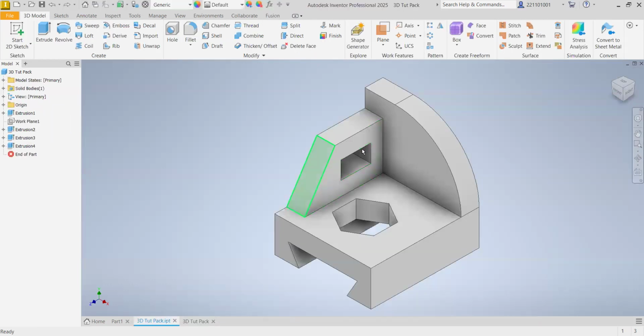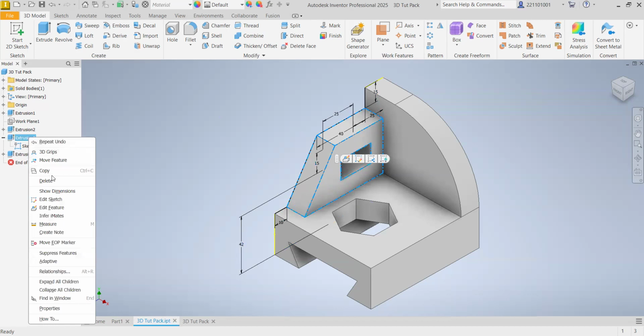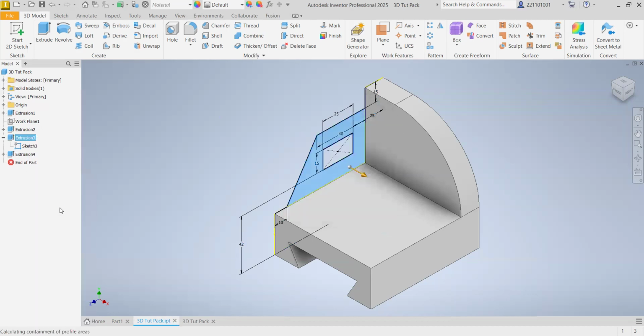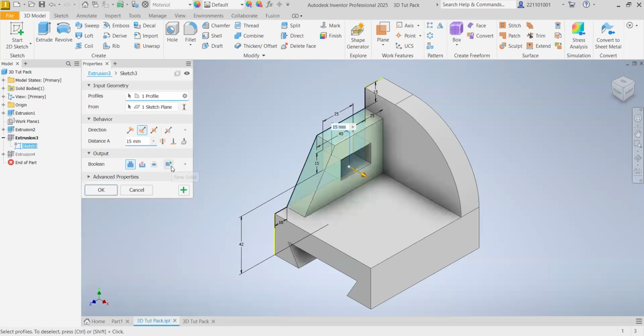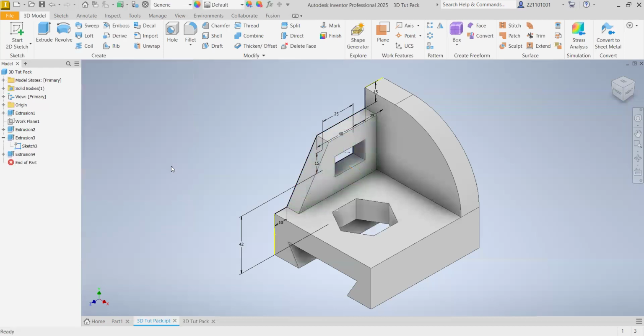You have to click on that part and say make sketch visible. That's what I want to correct. But you will remember that this part was extruded from here to the side. So you have to go to, yes, that's the extrusion that I want. Open it. That's three. Okay. Then right click. I want to edit the feature. I want to extrude that part 10 millimeters.